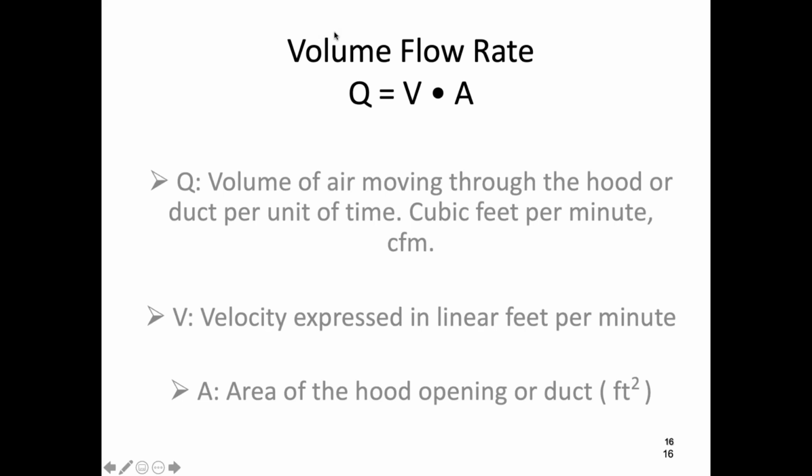So it's half a foot squared, a quarter of a square foot, times 3.14, right? So it's about maybe 0.8 square feet. The velocity of 100 times the 0.8 would make that about 75 or 80 cubic feet per minute. So that's the conversion.